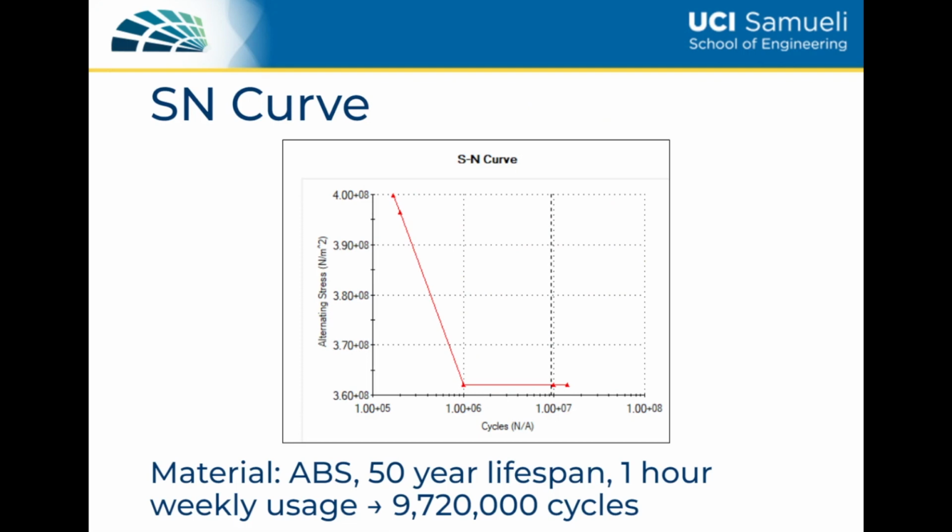In the SN curve, our values were unable to be plotted due to the low alternating stresses in comparison to the strength of the material, so we know that it definitely does not fail to fatigue.